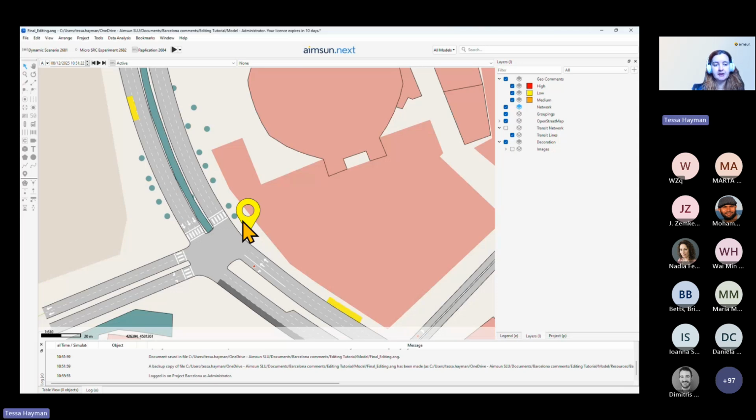And then I obviously need to say it's fixed. So I'm going to write in another comment to say I have fixed it. It's got the date that has happened so people in the future can know that. I then need to create a layer for it being fixed. So I go to new layer up here. I write in a name, so I'm going to call it fixed. And then I need to use style and layer, choose a brush, and I'm going to make it green.